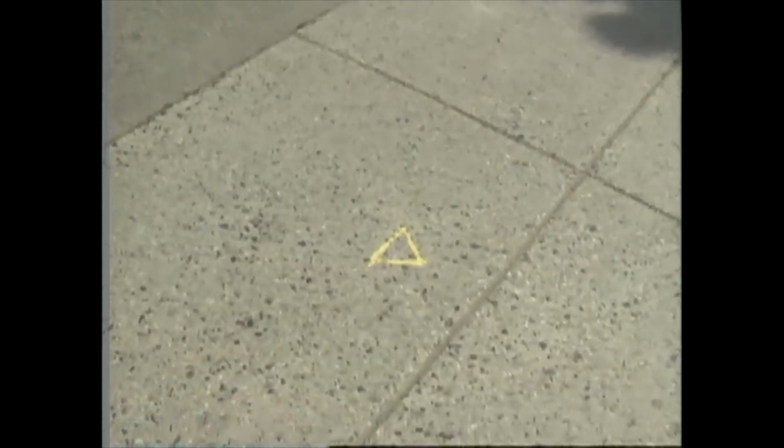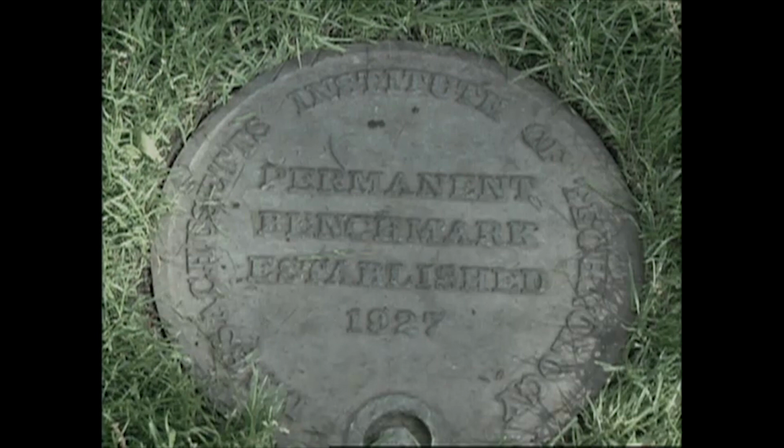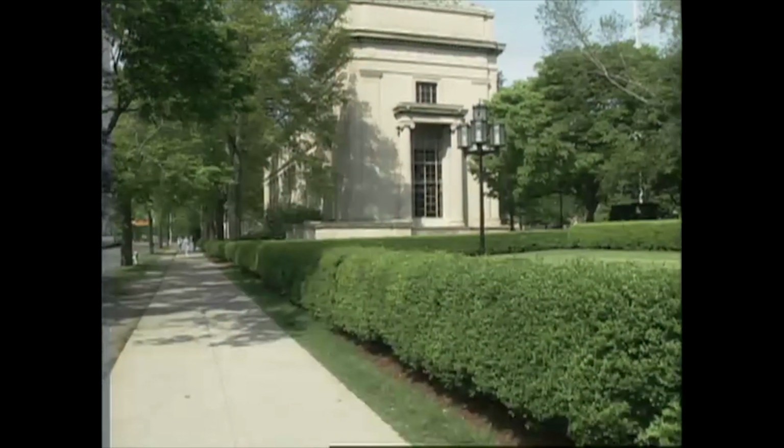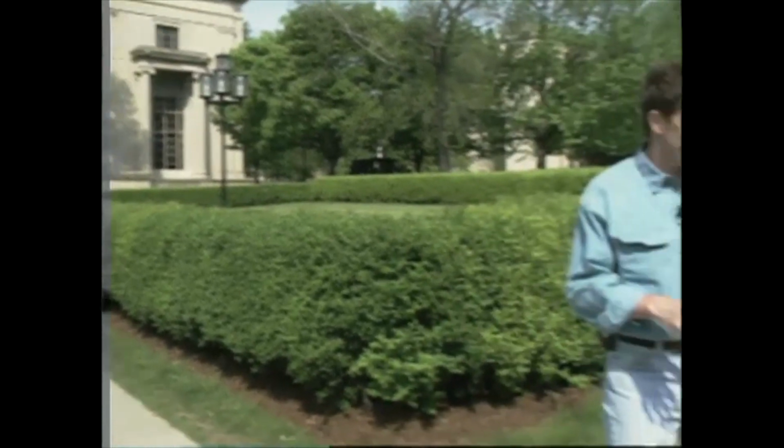Well, what we did was we established a point over here which has a known position, and we also established an elevation on that point by turning on it using differential leveling techniques from a deep benchmark which was established in 1927, located near the corner of this building right behind us here. Okay, so we know the height of this point, and we can then measure the difference between this point and the top of the dome. Yes, utilizing our total station instrument, we can establish a difference in elevation between the sidewalk here and the top of the dome.